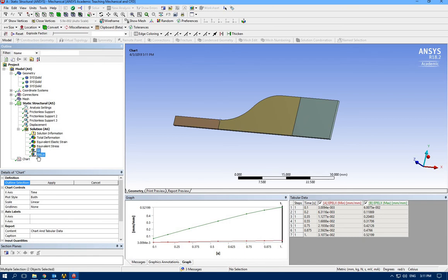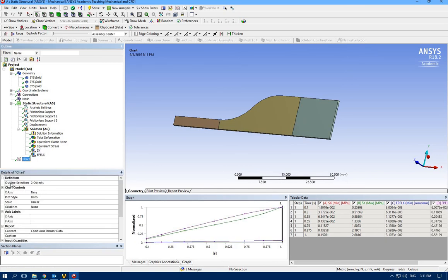So I have these two objects selected, and I'm going to apply here. So outline selections are going to be those two results I generated as user defined results. So stress as extraction, strain as extraction. What am I looking for? I'm looking for a stress strain graph.